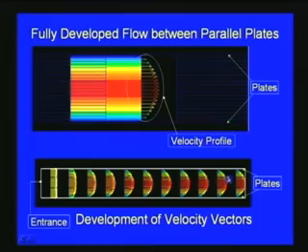So, this is the way in which we consider the Navier-Stokes equation to get some of the analytical or exact solutions. The case which we have seen is the plane Poiseuille flow problem. For this typical problem, there are two fixed plates and the flow is between them. You can see that the fully developed flow develops like this, with the entrance here.